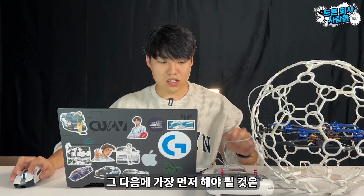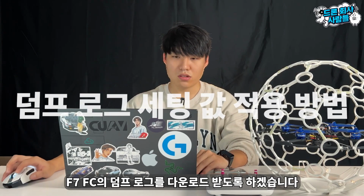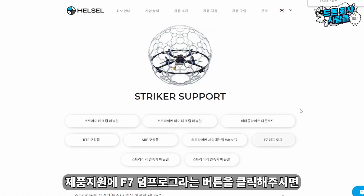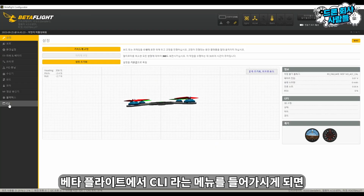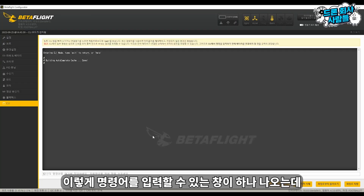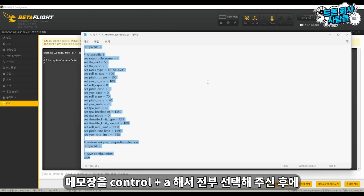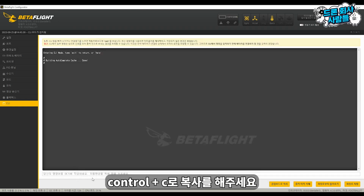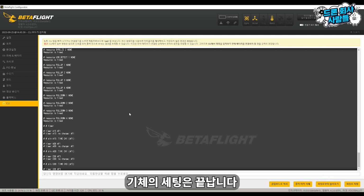The first thing to do here is to download the dump log of the F7FC. So click the button labeled F7 dump log in product support. Notepad will be downloaded. When you go to the CLI menu in Betaflight, a window where you can enter commands will appear. Here, select everything in the Notepad by pressing Ctrl A, then copy everything by pressing Ctrl C. Then, in the command input window, press Ctrl V and hit enter, and the setup for the aircraft is complete.